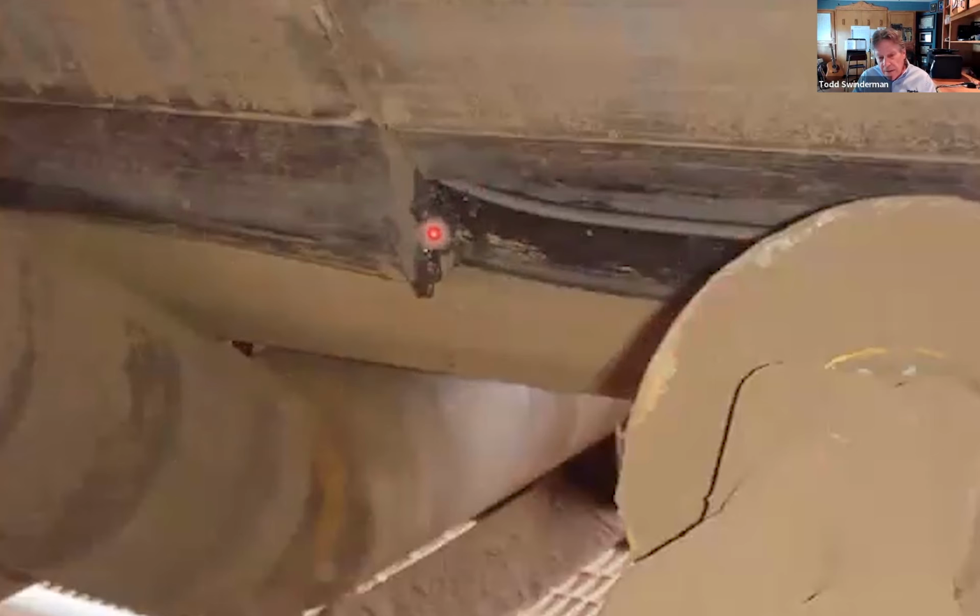And if you don't have enough mistracking allowance, what happens universally, doesn't matter what sealing system you have, if that belt tracks out from underneath your seal, when it comes back, the belt edges have a tendency to curl up and it goes up inside of your shoe. And I've even seen it where it rolls the belt completely over.